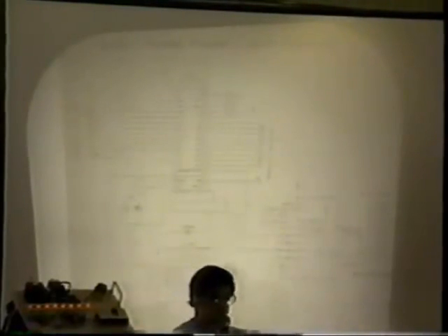Now, if you want to go serially, you got to put one behind the other. You have to add a stop bit. You have to add a start bit. You have to have a parity bit. You got about 11 bits there. You're sending out one after the other. And then that has to be converted back to parallel, because the chips, most of them want to work in parallel. Your computer wants to work with parallel, all 8 bits at the same time. So here you are slowing things down to 1/11th of the real speed that you can get, and it's really slow, and you must add the extra circuitry.